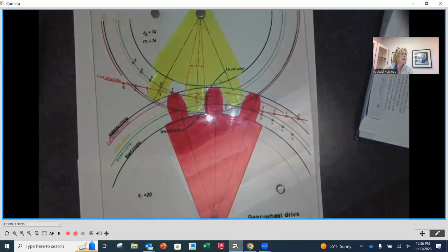And like I said, if we have a 20 degree and a 25 degree pressure angle, even if the diametral pitch is the same, they do not mesh together. They have to have the same pressure angle always. And that's part of what we do when we specify gears. We have to specify the pressure angle as well when we call it out.